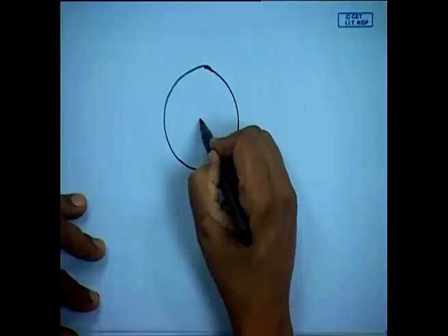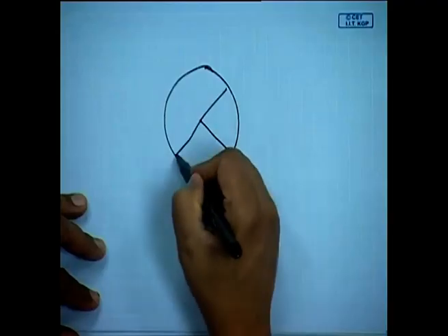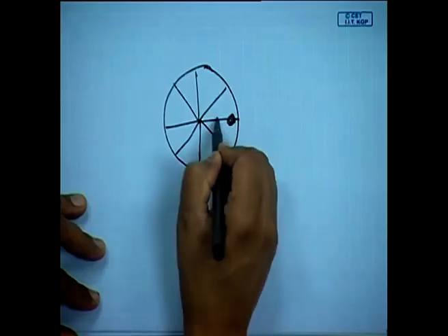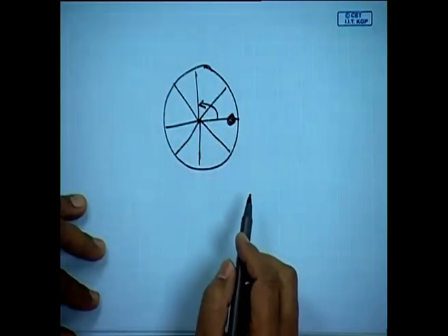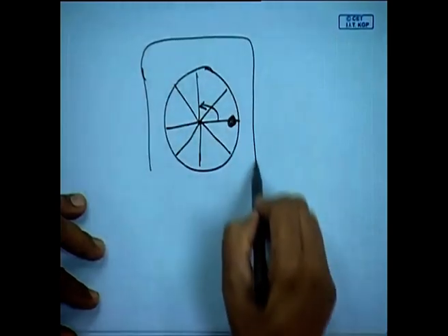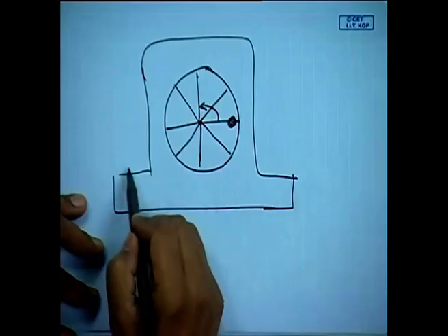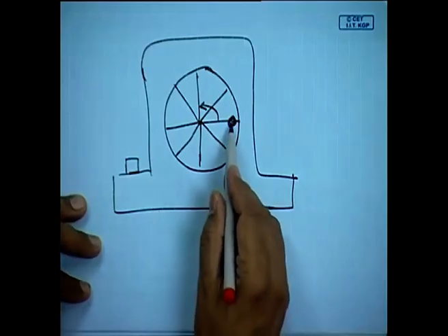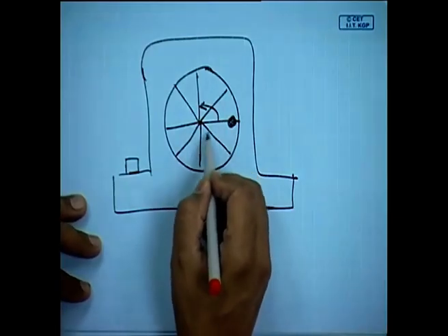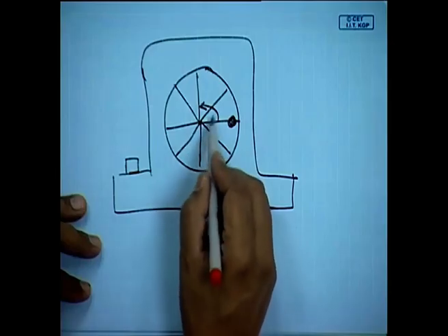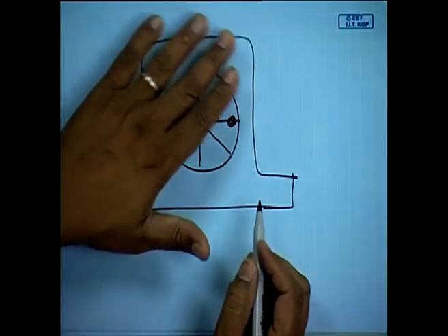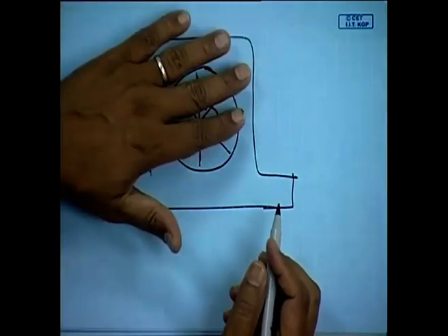Basically, what happens, I should briefly tell you here in the radial plane. For example, if this has a lot of vanes, blades, whatever. If there is a small amount of unbalanced mass and this is rotating, in this machinery, and of course in a casing, and I measure this response here. By some technique, if I can find out this amount of unbalance, and if I know the location of this unbalance physically with respect to a certain marker in this vane, I could put a correction mass in a single plane, and then I will have a balanced rotor or a balanced disc.